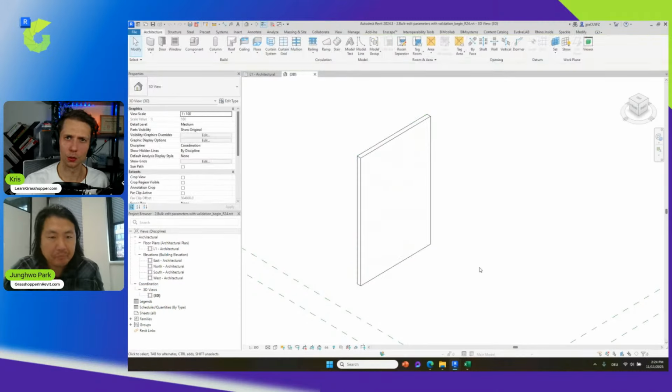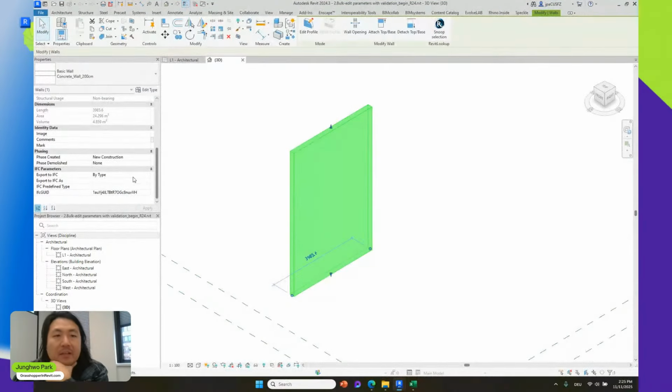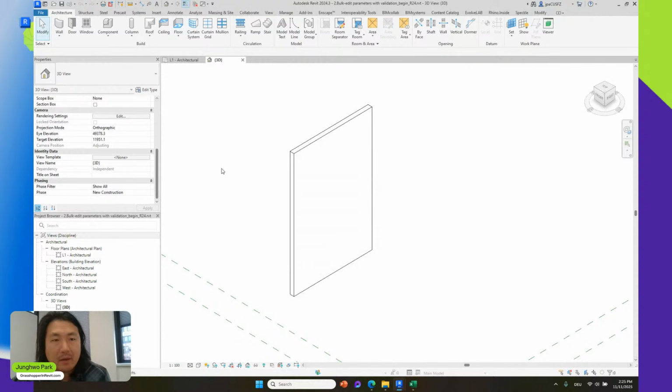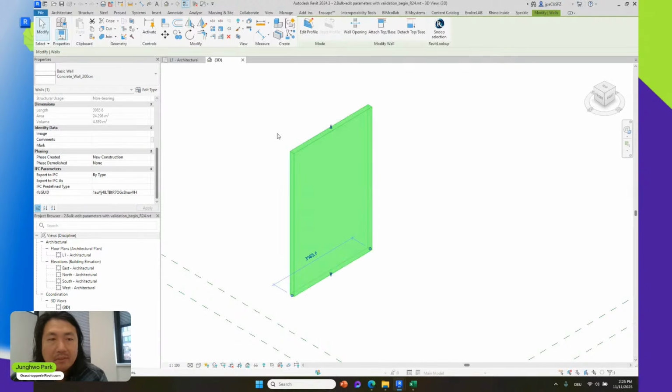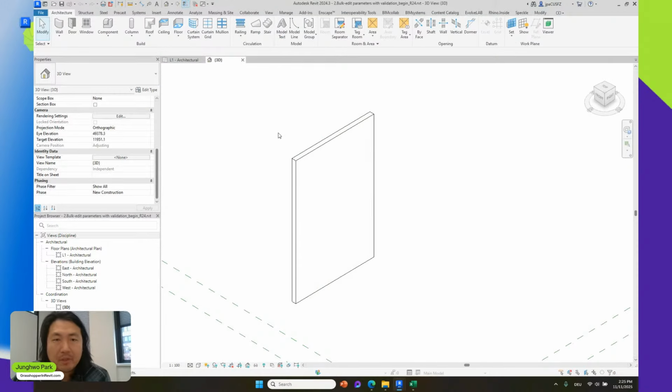So we have a wall. Yeah. One of the things here in Revit, which I often find a struggle, is having correctly structured IFC data for the open BIM workflow. Of course, you can create a bunch of project parameters from the shared parameters, but sometimes the manual process is tedious, and not everyone is allowed to create the content within the organization. But this topic is more for the content managers or information managers who need to have consistent information.